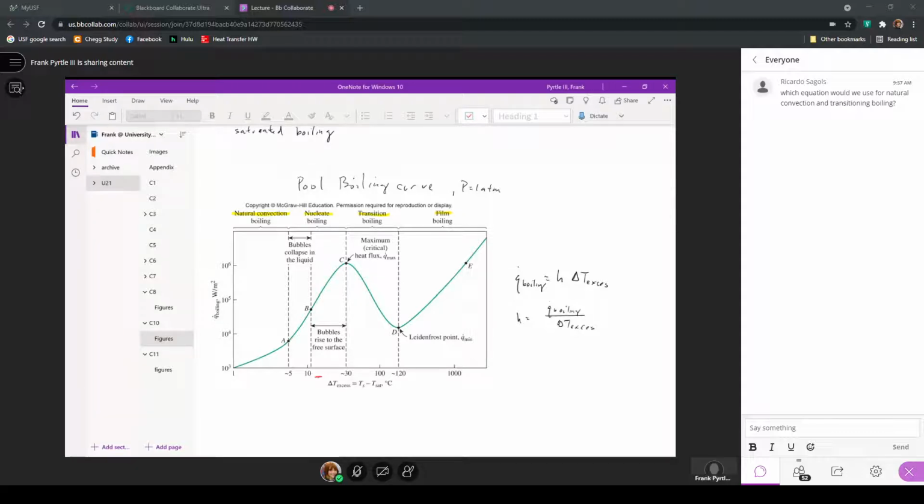So here we can use this expression and consider a temperature difference where the surface is at 125 degrees and the saturation temperature is 120 degrees. For this problem, there's a 5-degree temperature difference. That would definitely put us in the nucleate boiling range and not the film boiling range. So when we're looking at correlations that would describe heat transfer occurring from this surface when bubbles are being formed, and we only have a 5-degree temperature difference and bubbles forming, that says we're definitely in the nucleate pool boiling regime, not the film boiling regime.